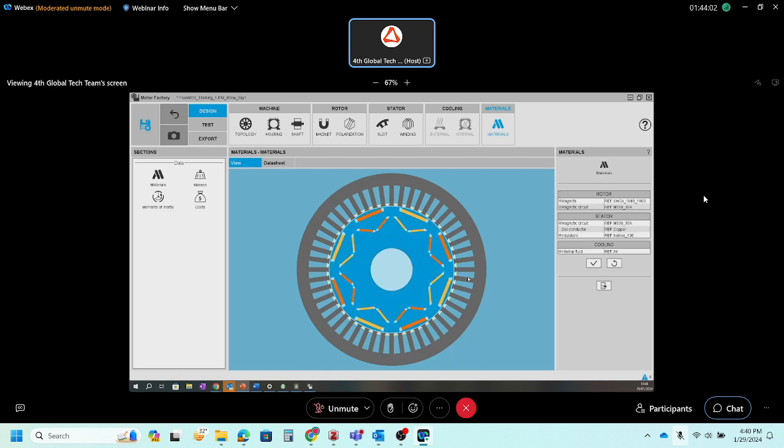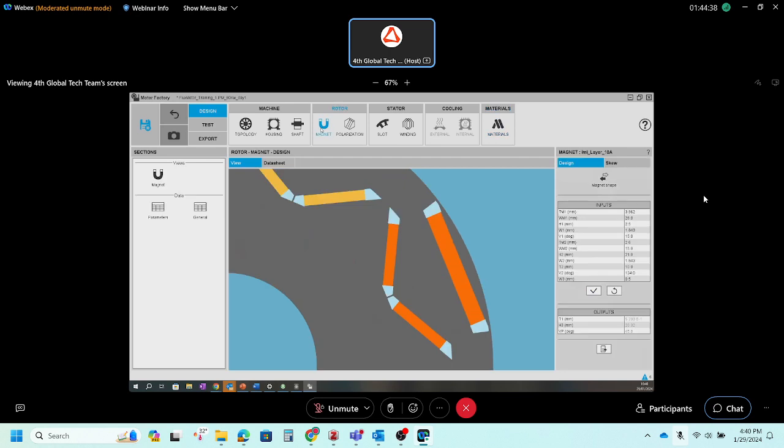Okay, we need to change the material for the magnets. We need to have a neodymium magnet. So the ref is this one, 1,230, 1,400. Okay, the magnet circuit instead is the same that we have here. The coil conductor are made by copper, and we also have Nomex as insulator. Also, the thermal fluid can be left as this one. Okay. We need to click on OK to make effective the modification, and I can come back to the magnet